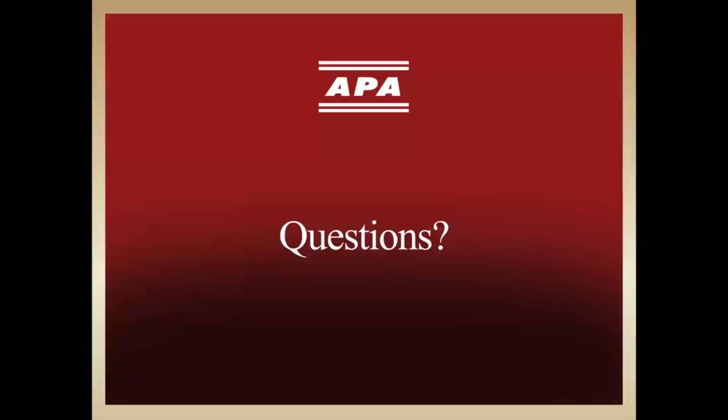What is the APA doing to educate builders with regard to I-Joist fire protection issues? Well, this question, of course, relates to the IRC, or International Residential Code, requirement that's been adopted recently in some states. It requires fire protection in most lightweight floors, including web wood trusses, I-Joists, and of course steel framing. We've recently added several new assemblies to our systems report, which is SR 405, and we'll have a webinar coming up that will be dedicated to that topic. Stay tuned, and we'll post details on our website for that.